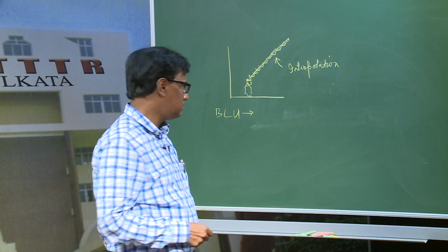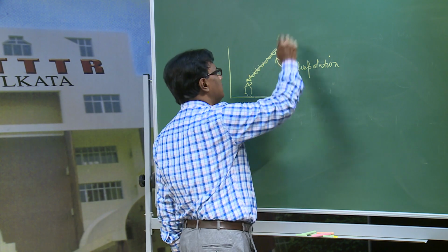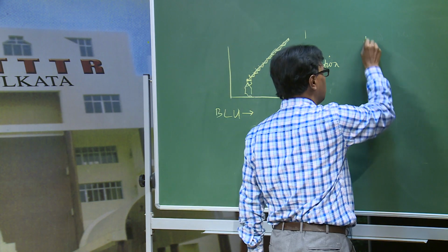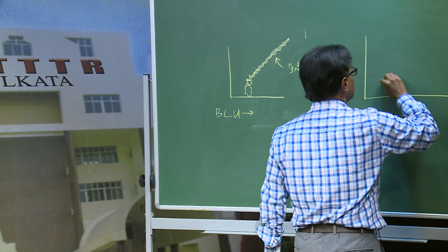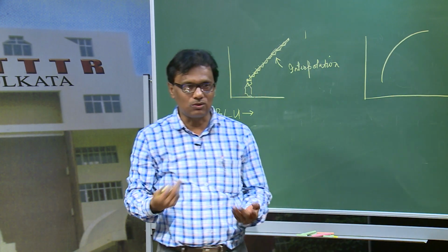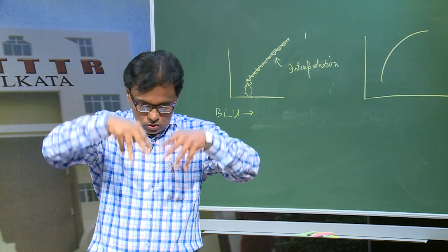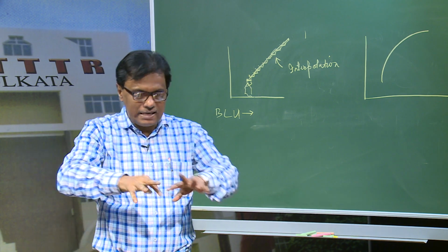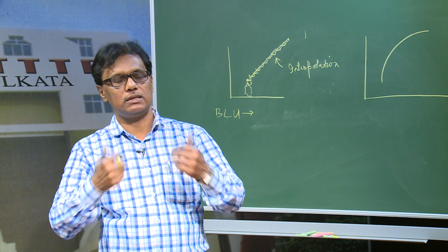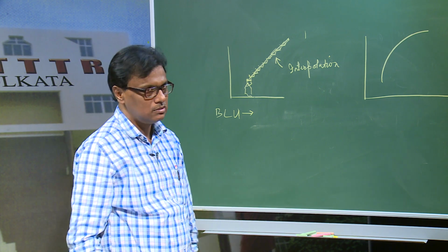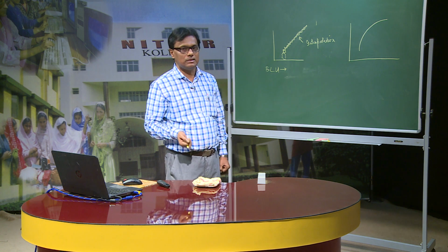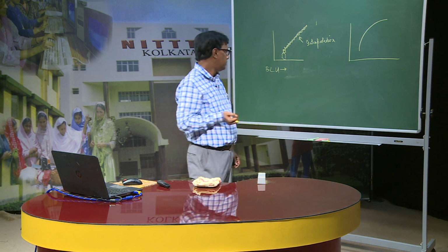This is the linear interpolation. In case of contouring, it is circular interpolation. If you cut a three-dimensional surface like in milling machines, it is spherical interpolation. So, interpolation is a very important factor in CNC machines.